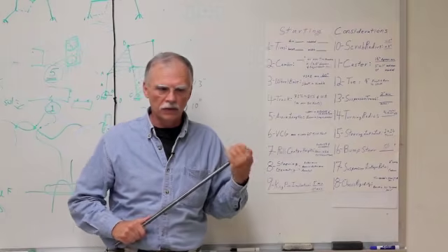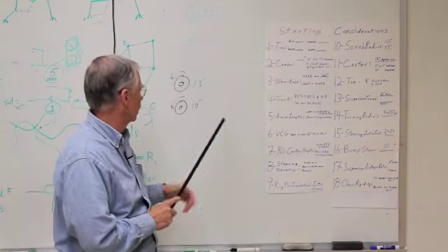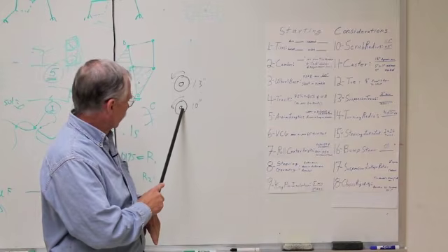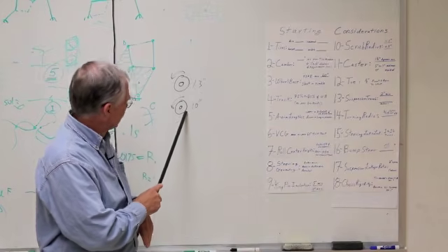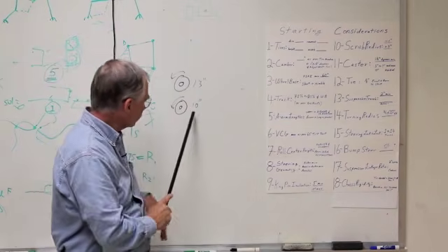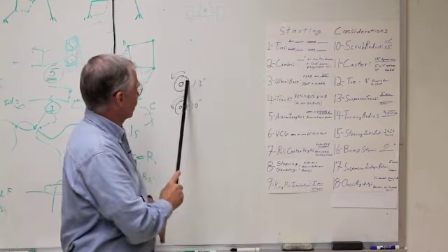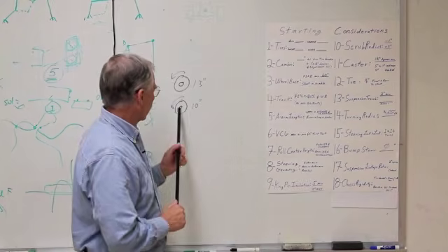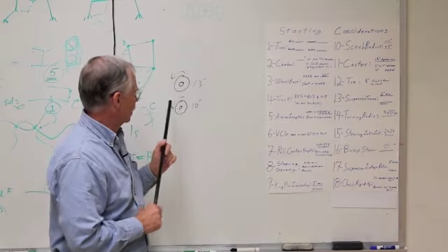My personal preference, if I was starting from scratch and had the budget, I would go with a 10-inch tire. Then I would try, especially if I could get a 10-inch racing tire in the proper soft compound, at the same width I could get a 13-inch tire. If I could do that, I would definitely go with a 10-inch tire.